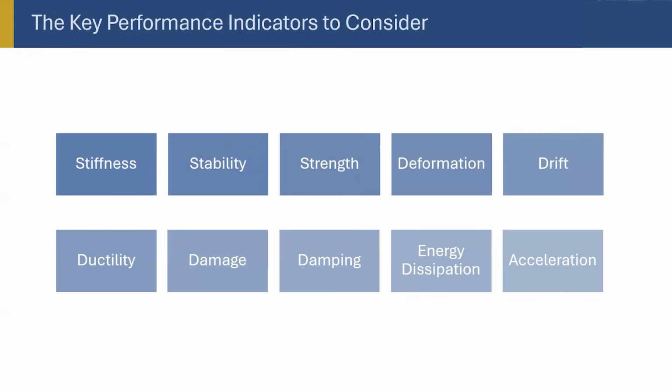This is a major concern during construction. Most of the things happen during construction, stability issues. And because the structure is not complete, we don't think about the incomplete structure stability. We rely on the temporary works and temporary formwork. That doesn't work, things fall down. So that's why we have to be careful about the stability during construction and post-construction.